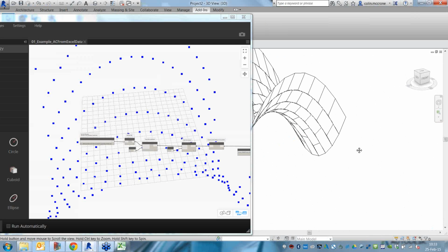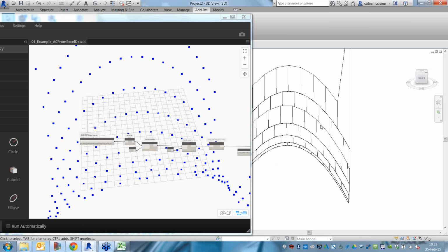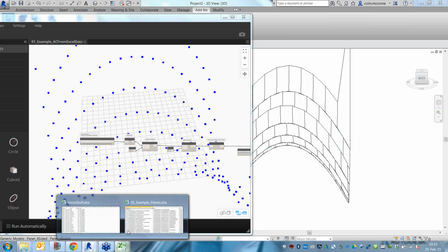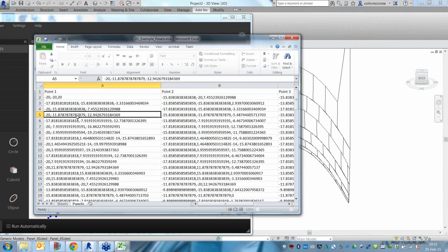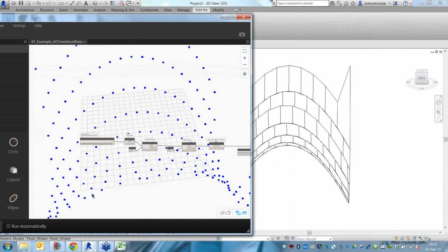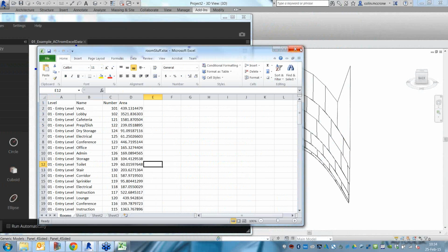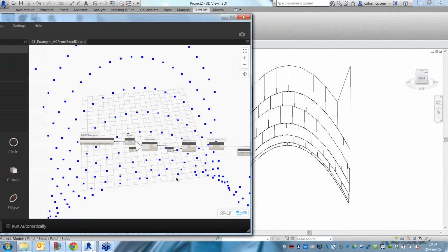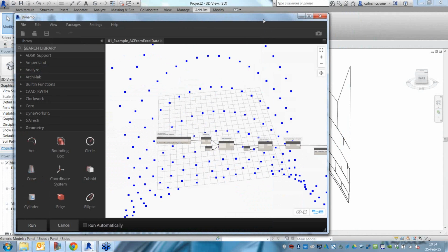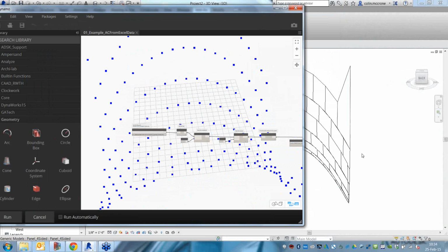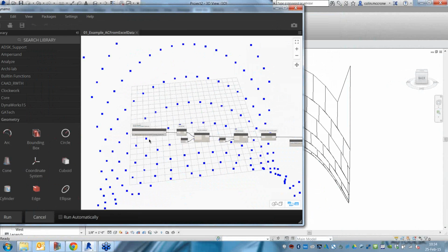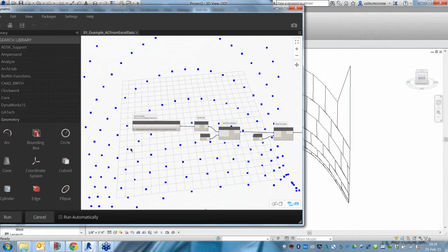Great. All right, we got one last question. This is more of a statement. I have old families in a project. I need to update them with new families named differently, of course. I can map old to new in Excel. Just need the insertion point and rotation angle extracted. Yeah, I think that's more of a statement, but that's possible today. Basically swapping stuff out. It's kind of like find and replace in other tools. You see people do that a lot.